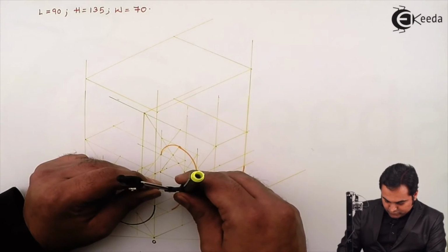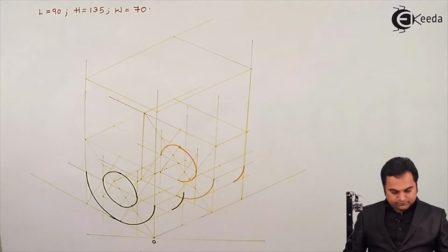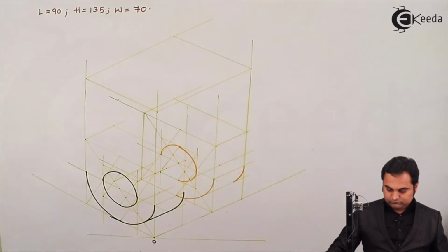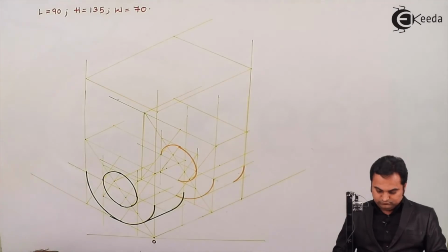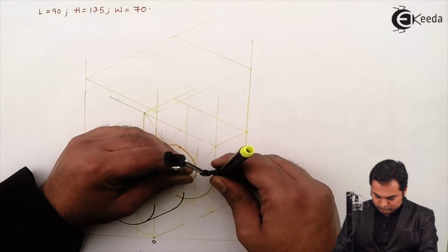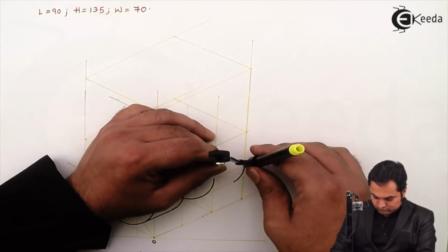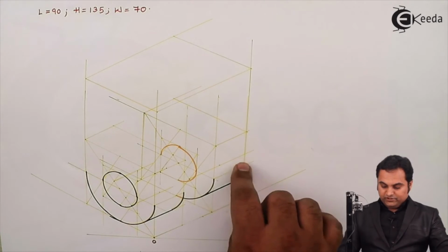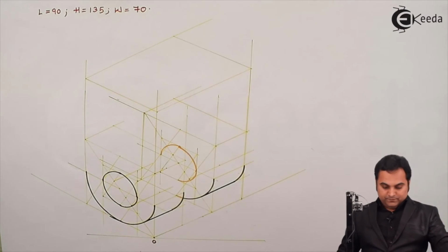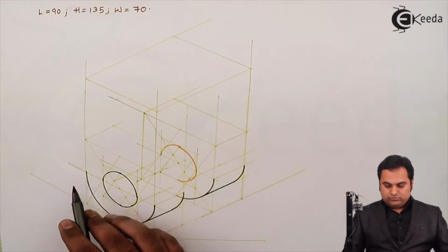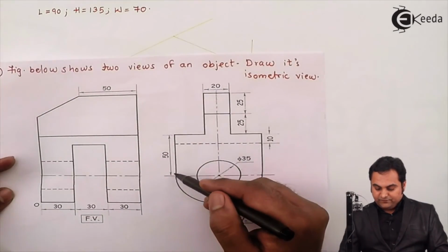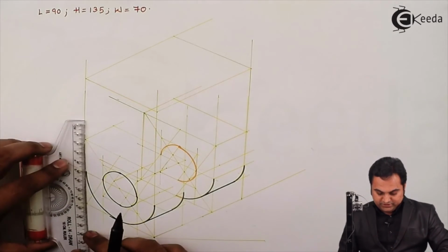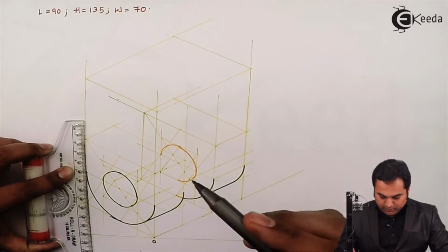Again this arc will also be dark, joining them with the help of a dark line. Next, after reaching here, from the center to the top the distance is 50 mm, which is the height. So from this center, I am making it dark up to 50 mm height.